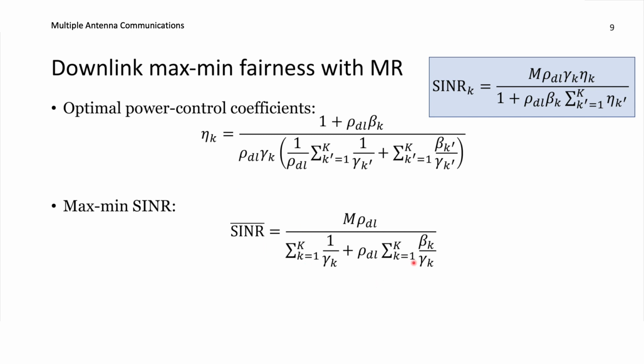And we can do the same type of methods for other types of processing than the maximum ratio. Then we need to play around with the A and B parameters, but we'll still have the same shape: the etas will sum up to 1, and therefore we should remove it, and we have an A and B term here instead. Then we should allocate the power first to make sure that those are cancelling out each other, so that everyone gets the same value, and then we should maximize that same value by scaling up the power so we are using the full power in the end. So this is the expression that we're getting.